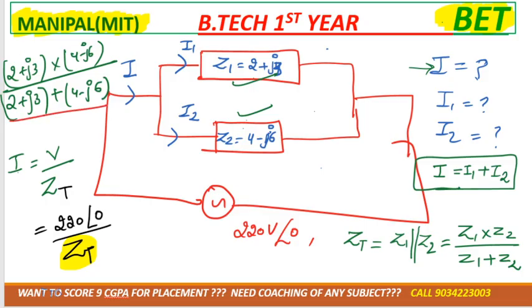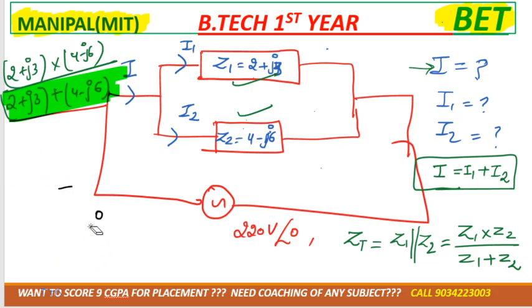So in the denominator, as you can see, we'll have 2 plus j3 and 4 minus j6. It's in the rectangular form, so you can do it directly. क्या आ जाएगा बताओ मुझे, tell me. Real term is added with the real term, 6. Imaginary term is added with the imaginary term, so it would be 6 minus j3. ठीक है?